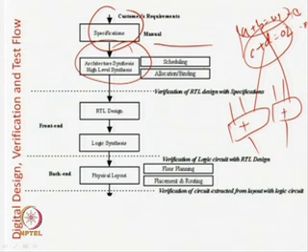So, the basic idea is that we are making a block level diagram of a specification to satisfy that specification, and we are answering questions like how many adders are there, how many multipliers are there, which operands will go to which operator and so forth. Once that is done, we go for the RTL design and logic synthesis.